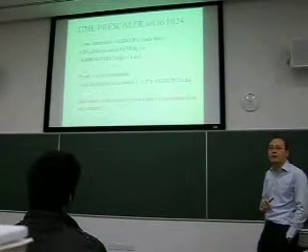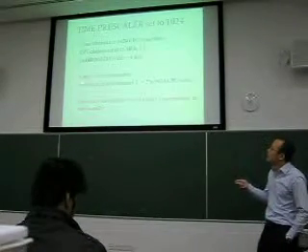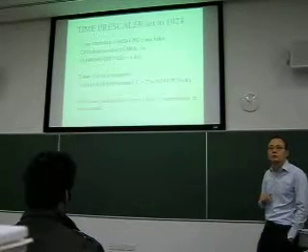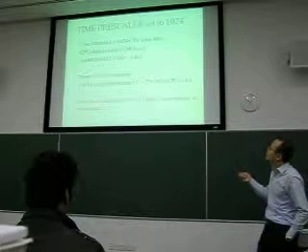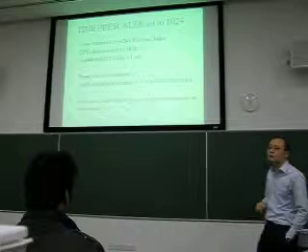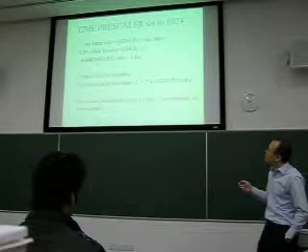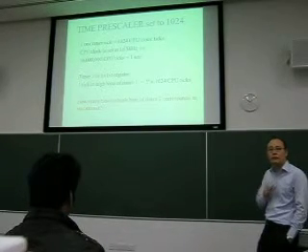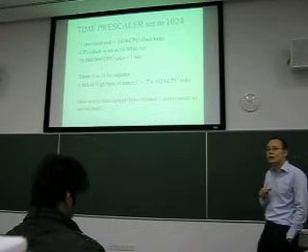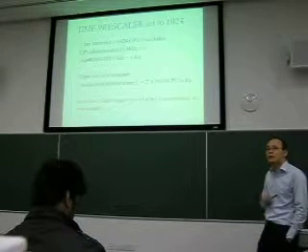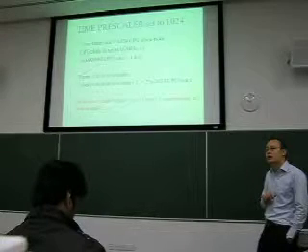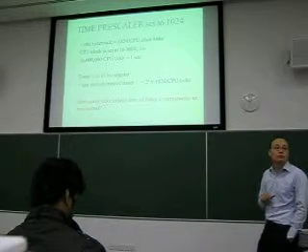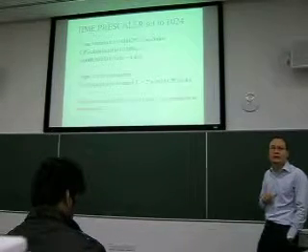Bits, right? Timer 0 is 8 bits, but at the moment we're just concerned with timer 1. And I told you 1 tick in timer 1 corresponds to 1024 if we set it that way. Okay? But timer 1 has 2 bytes, right? The lower byte and the higher byte. So the least significant bit of the higher byte, what is the value of that? 256, right? Does everyone understand this?